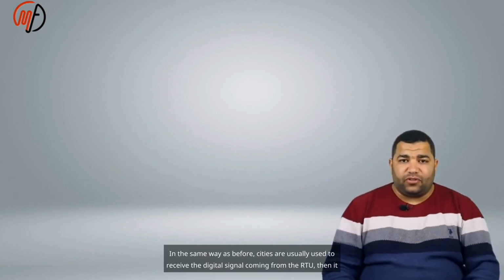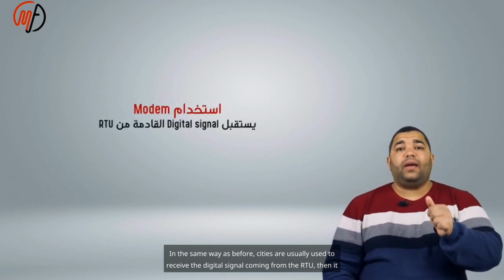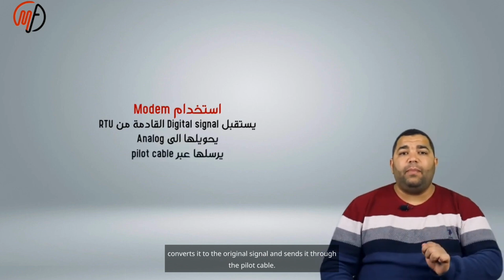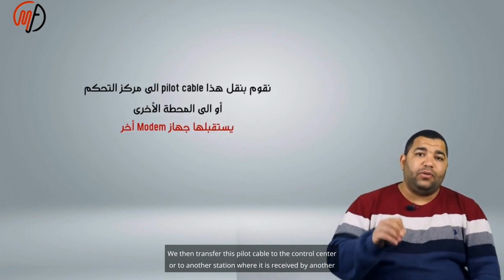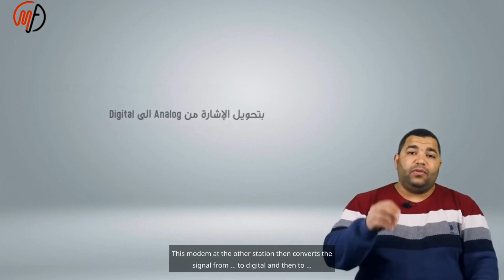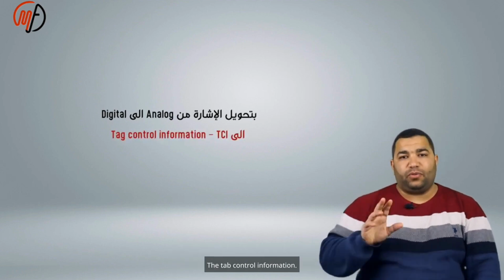In the same way as before, modems are usually used to receive the digital signal coming from the RTU, then convert it to the original signal and send it through the pilot cable. We then transfer this pilot cable to the control center or to another station where it is received by another modem. This modem at the other station then converts the signal to digital and then to the control information.